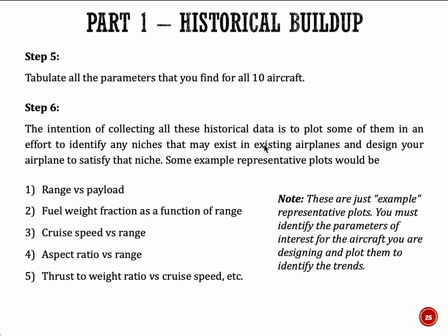The intention of collecting all this historical data is to plot some of them in an effort to identify the niche that may exist, or gap in existing performance, right? And you will be designing your airplane to satisfy that niche. So depending on what aircraft you're looking at, these are some representative plots that you can plot: range versus payload, fuel weight fraction as a function of range, cruise speed versus range, aspect ratio versus range, thrust to weight ratio versus cruise speed. But just don't stick to these five, okay?